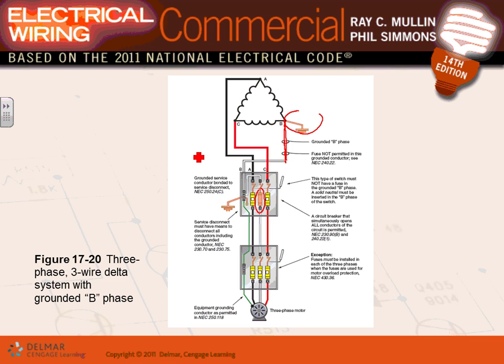So Karen, you have a fuse disconnect here with 2 fuses and a piece of copper that looks like a fuse stuck in the location where the fuse is supposed to be. Because by code, you cannot open a grounded conductor unless you simultaneously open the other ungrounded conductor with it.